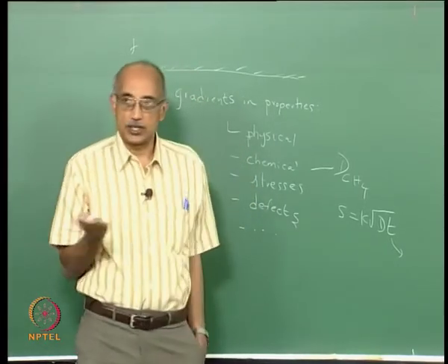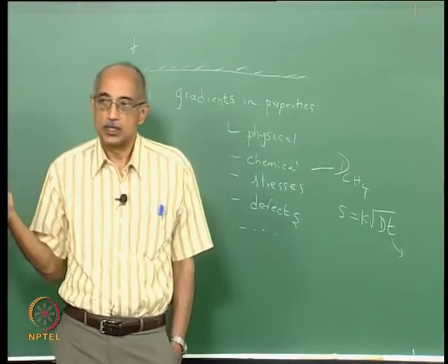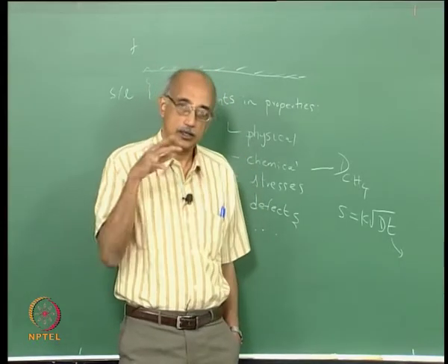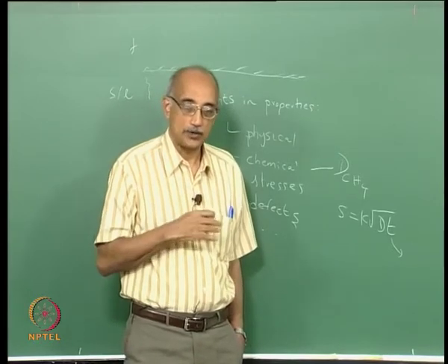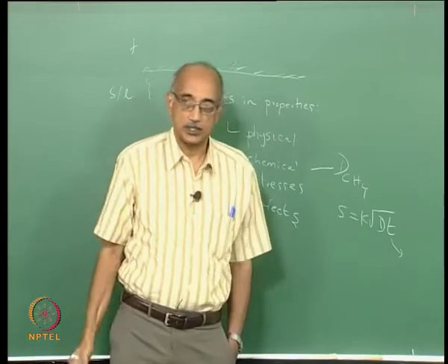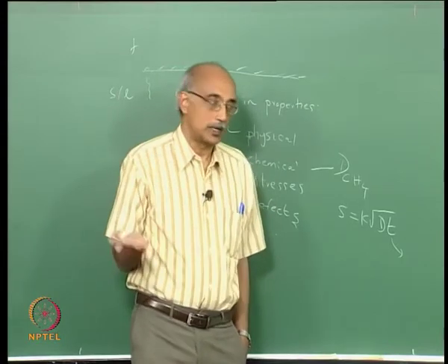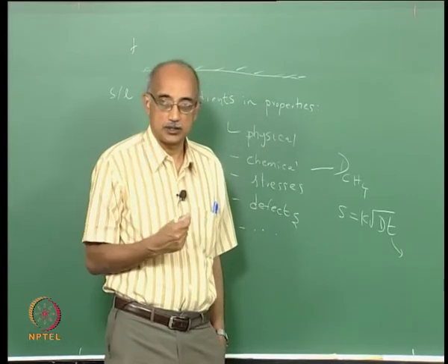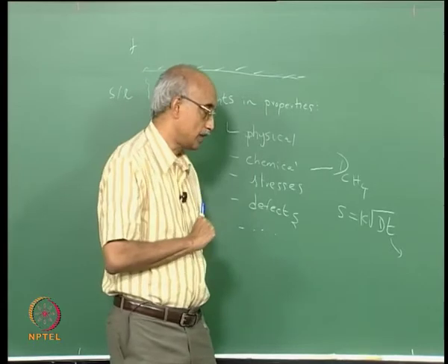Another example would be nitridation. Again, you want to add nitrogen to an alloy material. This is typically done by pumping nitrogen gas over the alloy under pressurized conditions in order to improve diffusion rates and diffusion coefficients, and you will again see this type of behavior. It is basically a square root dependence. You take the diffusivity of the species, multiply it by the time, and take the square root. That basically gives you the time dependence of the depth of penetration by this reactive gas.